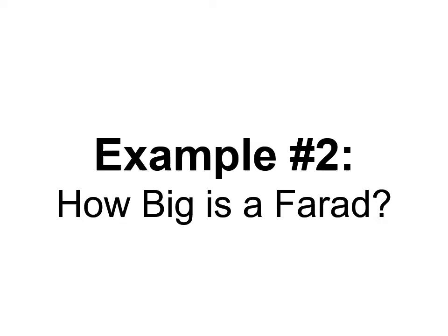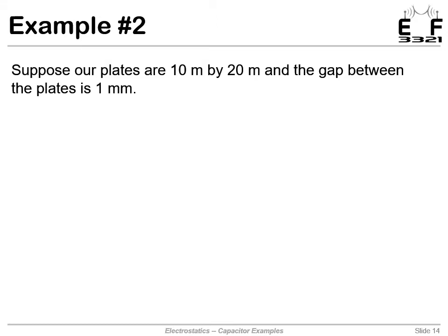Next example, how big is a farad? So let's design a capacitor that's roughly the size of a classroom. So let's say it's 10 meters by 20 meters. And let's let the gap between those plates be 1 millimeter. Physically, that's a very large capacitor. There's a lot of area there. What value of capacitance would we get from this? Well, we apply the equation for our parallel plate capacitor, and let's figure it out.